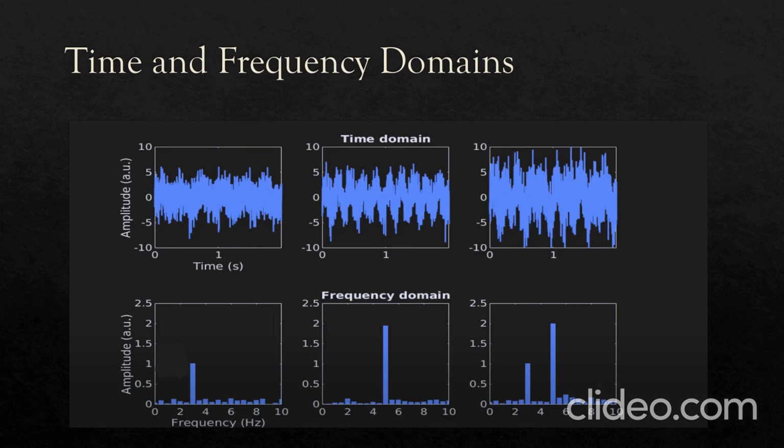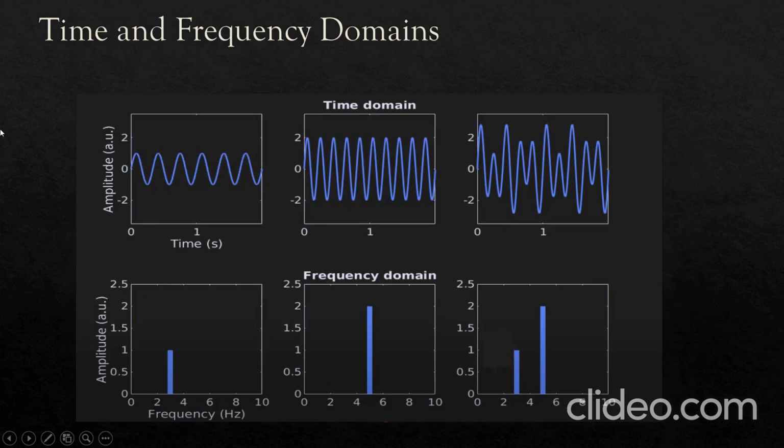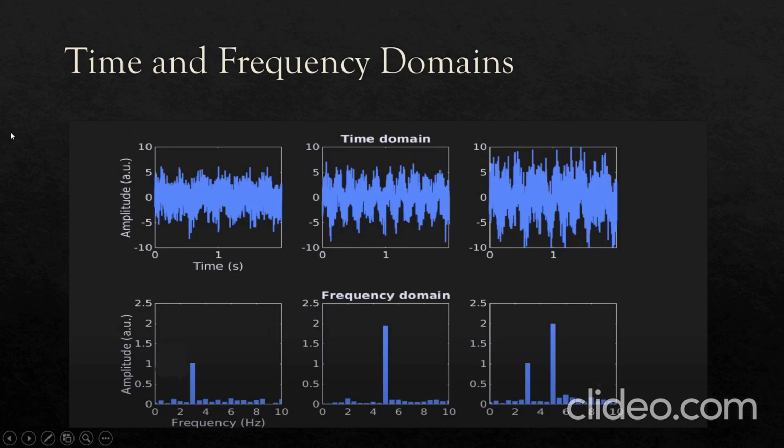One more advantage of the frequency domain would be getting rid of noise. The signals we see here are just the previous ones with random noise added to them. It would be quite difficult to even know the prominent function of the signal apart from the noise. But in the frequency domain, we can understand in a second that the prominent one is a sinusoid with respect to amplitude and frequency, and it has these background noises with low amplitudes at various frequencies. Since these broadband noises have a flat power spectrum, they are also referred to as white noise.